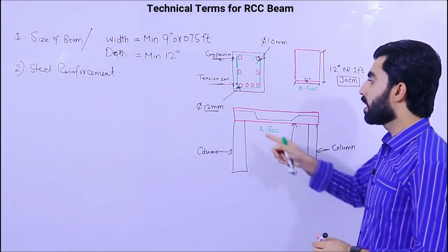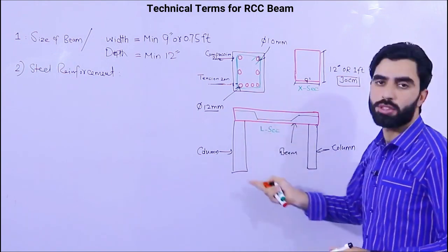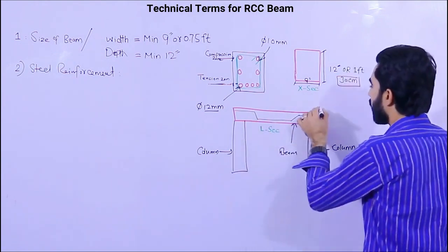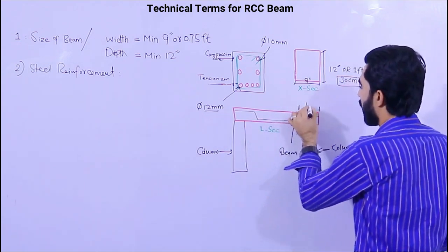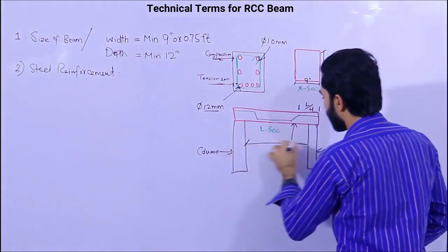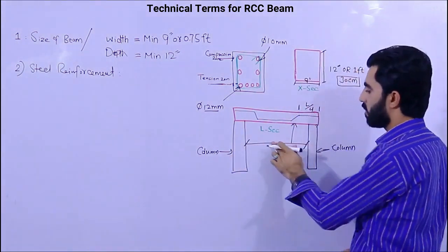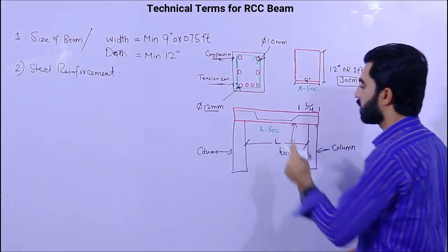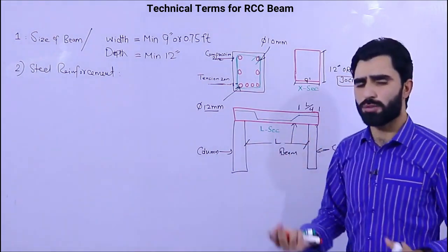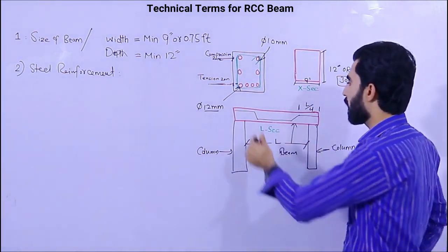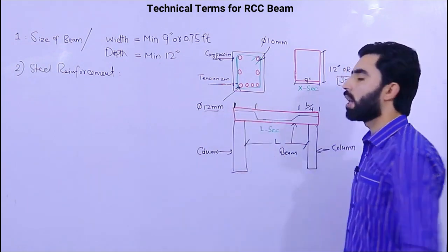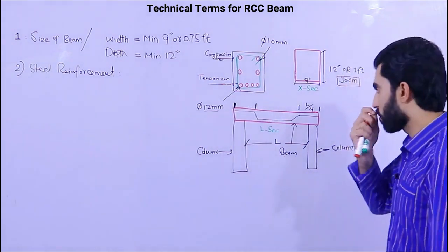And also remember guys, we can also use the cut piece method, or provide extra bars here with a distance of L/4. So this length should be L/4. Remember, what is L? L is the clear span. So the length should be divided by 4. If you get any value, 4 feet, 5 feet, 6 feet, or 1 meter, it should be the length of the crank bar. So this is very important to know.